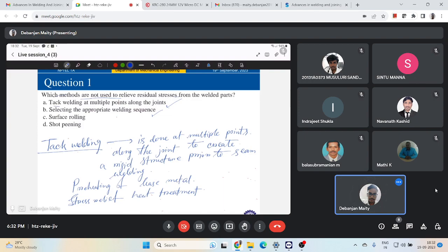Now, if you see the surface treatments like grinding, like milling, bending also, those things cause this tensile residual stress, right? And this tensile residual stress leads to this low life cycle of the parts. Now, what does shot peening do? Shot peening converts those tensile residual stress into compressive residual stress. That leads to a significant increase in the life cycle of the part and their maximum load capacity.